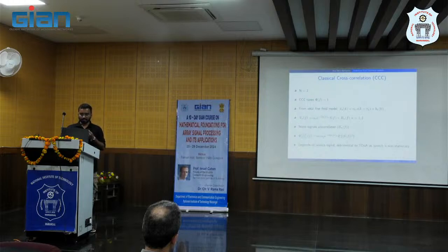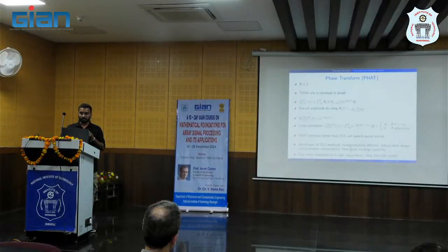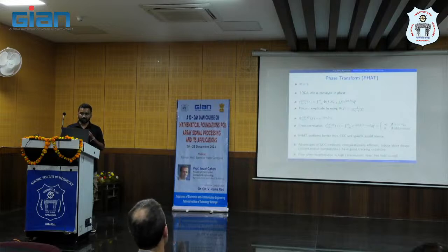When we take it as 1, the final signal depends on the magnitude of the signal. This depends on the source signal, and it might interfere in the final computation. The second choice is the inverse of the magnitude. When this is taken, the time difference of arrival is in the phase term.